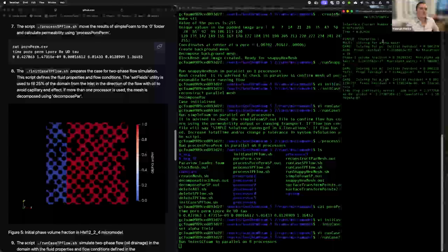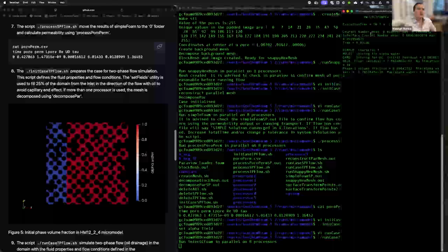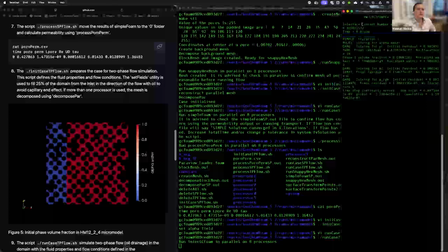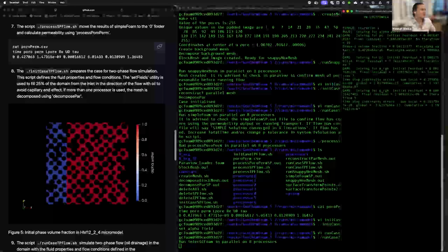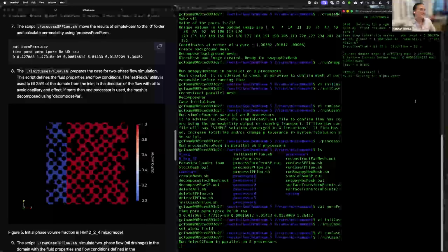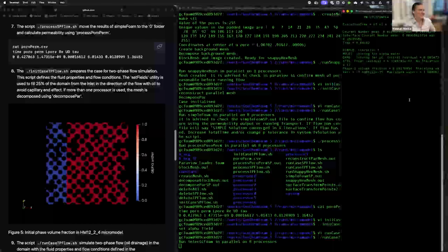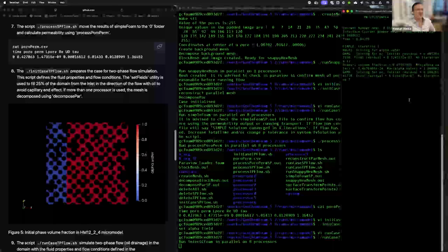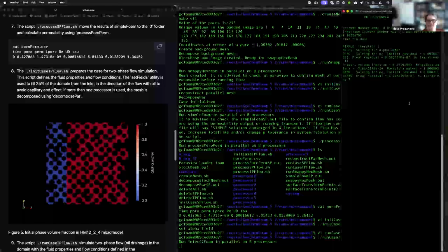Yeah, and you can see it's running now, and we're doing okay. Does anybody maybe want to hazard a guess as to what would happen if the Courant number went over 1? Does anyone know what a Courant number is? No? You'll get a whole bunch of not numbers. Yeah. So this is what controls our time step. It's what makes multi-phase flow so hard, right? Okay. Those of you who have been in the program longer...